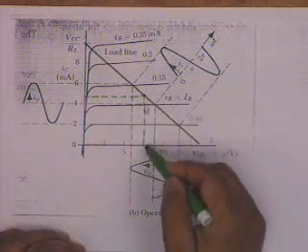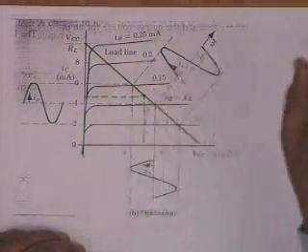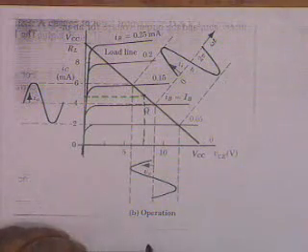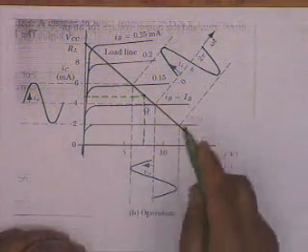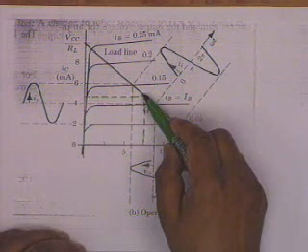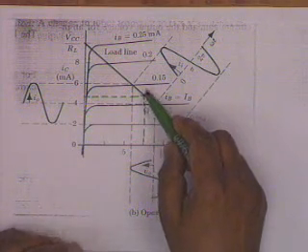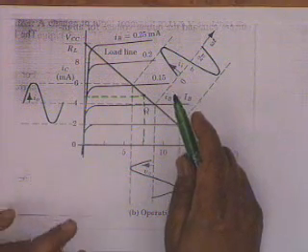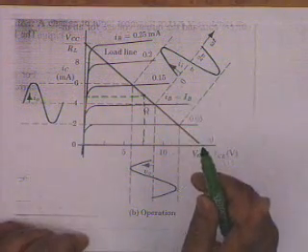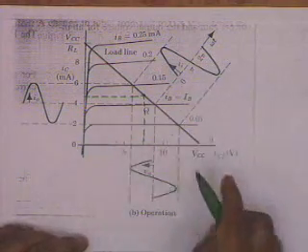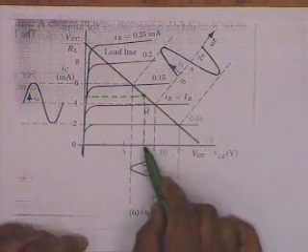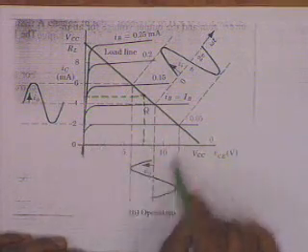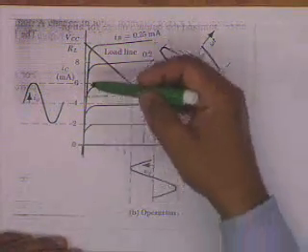If this is 7.5, the DC load line and AC load line are the same. In other words, there is no capacitor taking pure load. It's RC. Well, 7.5 volt is the Q point and therefore approximately the swing is how much? 7.5 volt. That means it can go 15 here and approximately 0 on the other side. So 0 to 15. What about the current swing?